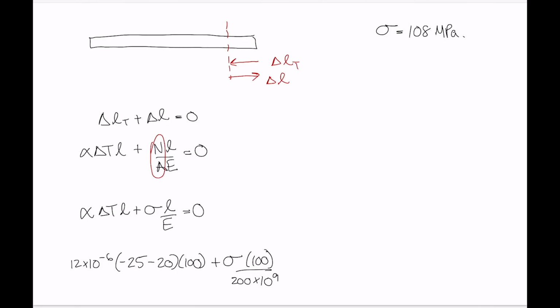Now we can use that expression which said that the maximum stress in the girder, which is equal to 108, is going to be equated to the yield strength over the safety factor. So we've got 108 megapascals times 10 to the 6 equals the yield strength, 250 megapascals times 10 to the 6, divided by our current safety factor.